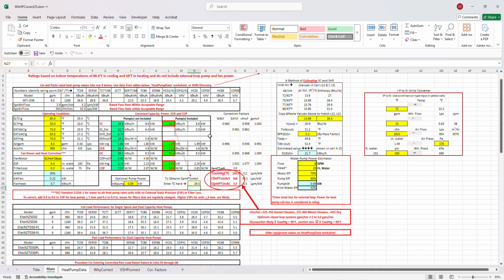So right, yeah. So we're right at 100, and the GPM, we could drop that down a little bit. Let's knock it down to 7. Okay, and that drops the, change this, and it drops the fan power down just a little bit. So we'll change that to 0.08. Okay, so now let's see what we got. We got a little bit below 100, but it's still pretty good. This is almost the same, so we're not going to change that too much. So we're looking at a 7.4 on the sensible heat ratio, and we got almost 100 degree air.